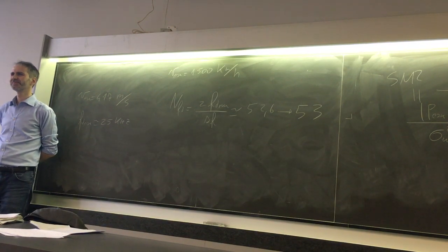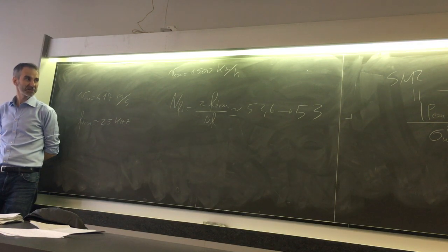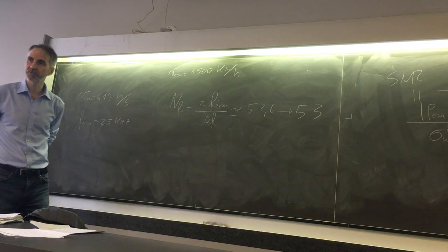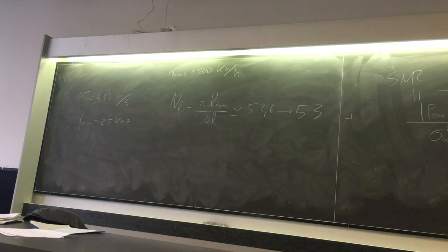What is the difference between the FD max that we have found and the condition on FD that we have found previously? FD max is the maximum Doppler frequency that we expect, because we say they cannot fly faster than that. We know that we will get a cardinal sine.